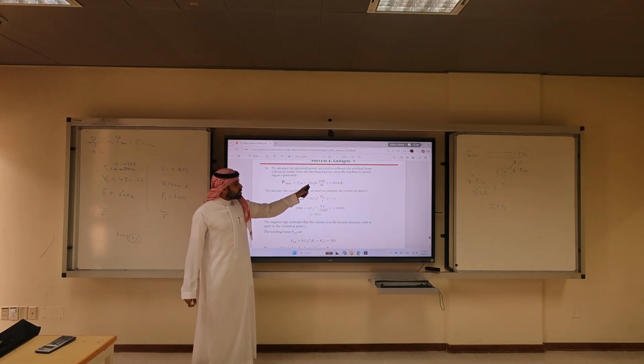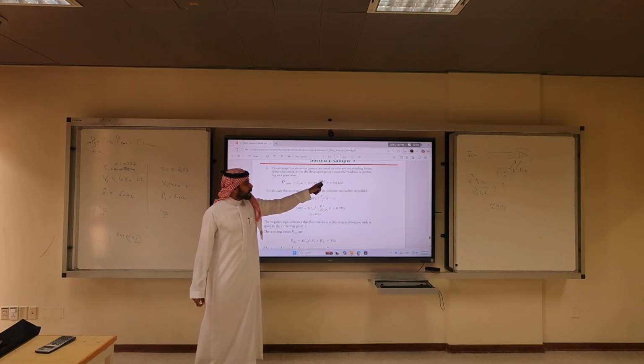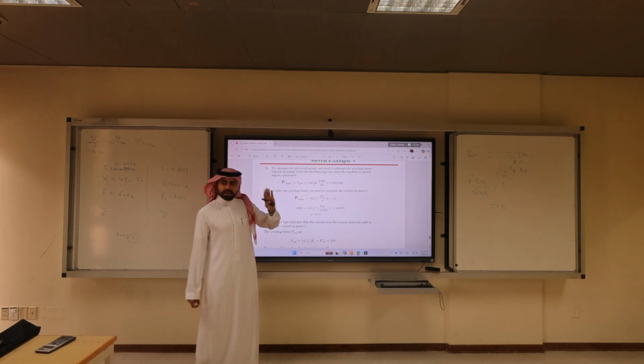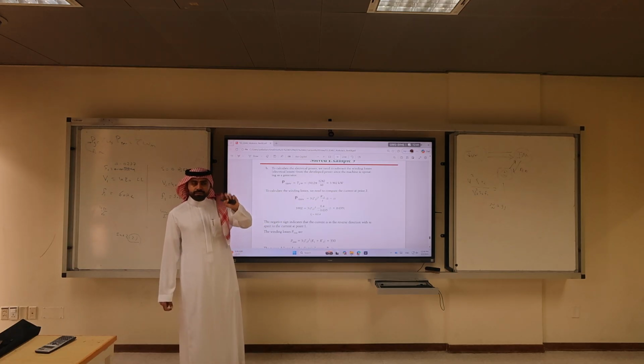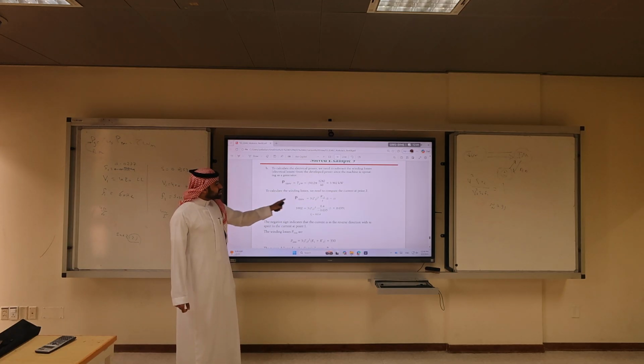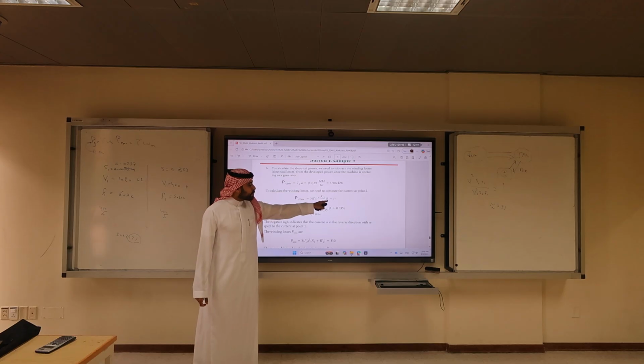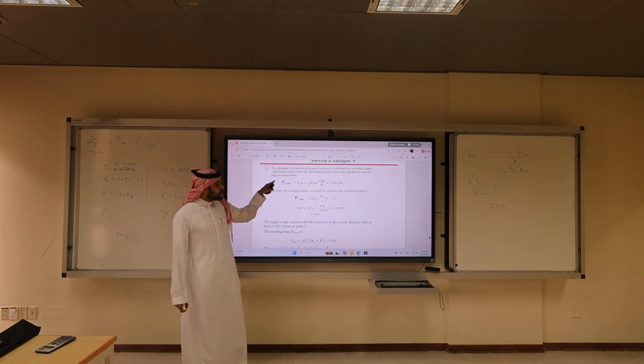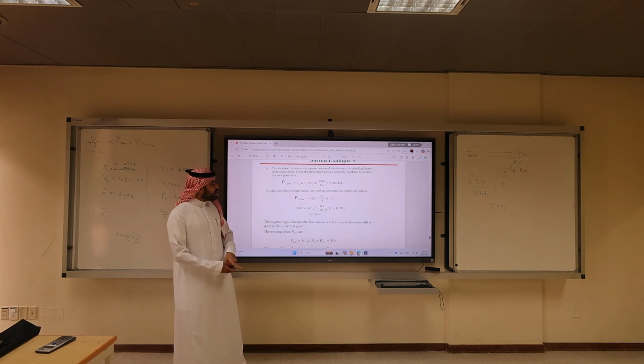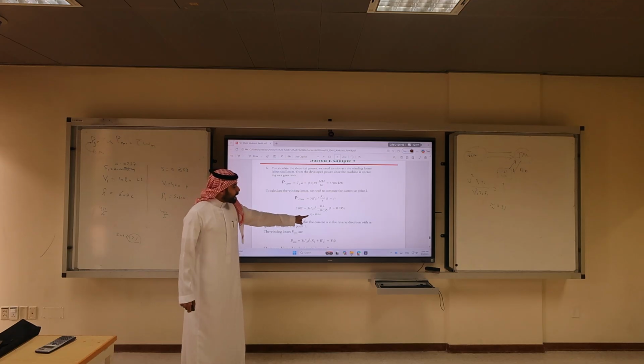So here we have 30 Newton meters. Then you apply that. You can apply a negative sign here, but you will confuse yourself. Then what is P converted? Another formula is 3 I2 squared R2 over S times 1 minus S. Why do we use this formula? To calculate the current. When I calculate the current, I'm going to calculate the copper losses and subtract them from this. Then I can calculate the power. So if I solve for I, it is 10.5 amp.